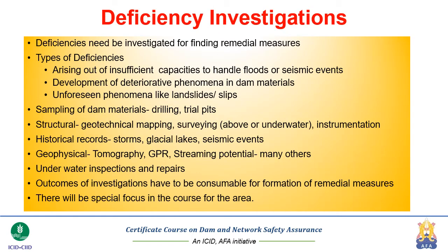Deficiency investigations for the dam is a very critical area. What is lacking? The dam will only exhibit a symptom. Dam will indicate that there are cracks here, that there are some deformation here, but then these are the signs, these are the symptoms. What has caused those symptoms is equally important. If those causative factors are not understood, then we may take some measures which may give us a temporary relief, but then again this phenomenon may come back in a virulent form.